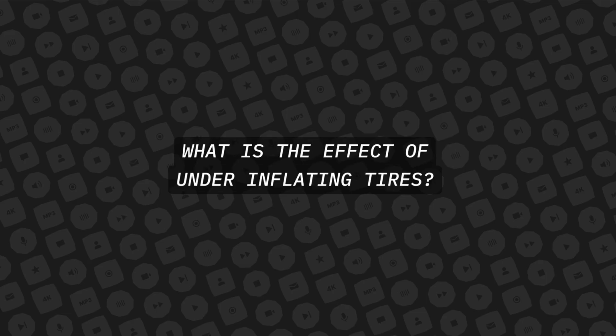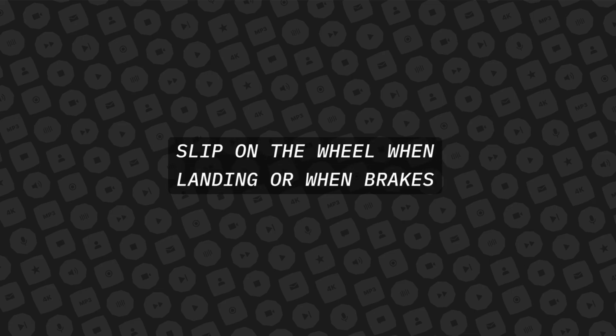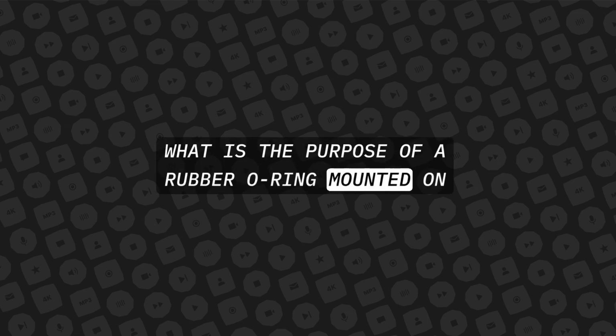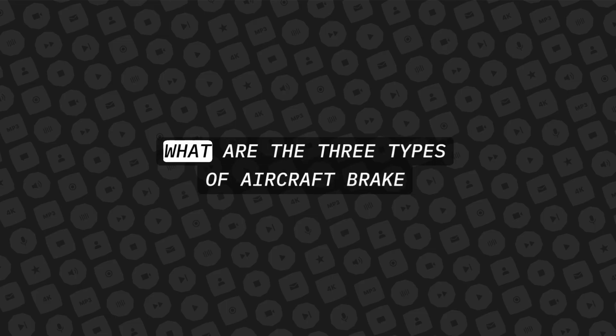What is the effect of underinflating tires? Underinflated tires are more likely to creep or slip on the wheel when landing or when brakes are applied. Underinflation also causes rapid uneven wear at or near the edges of the tire. What is the purpose of a rubber O-ring mounted on the mating surface of the outer wheel half of a split-type wheel? To prevent air leakage from the tubeless tire.